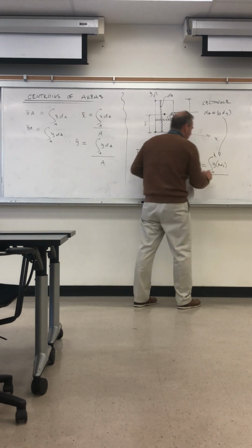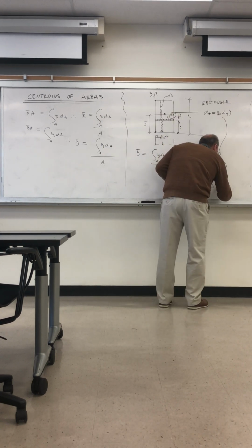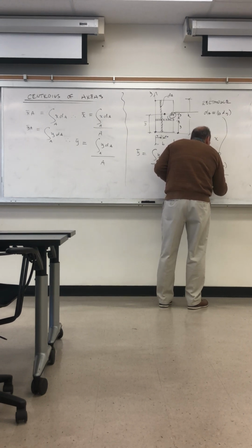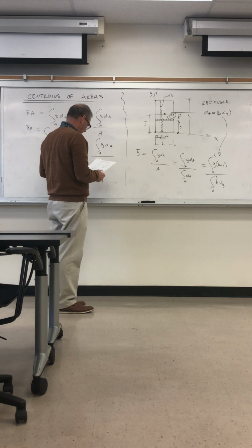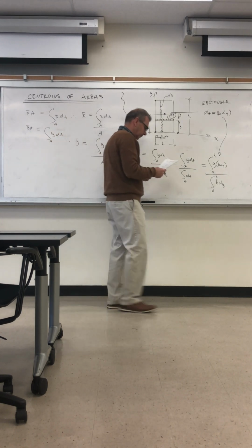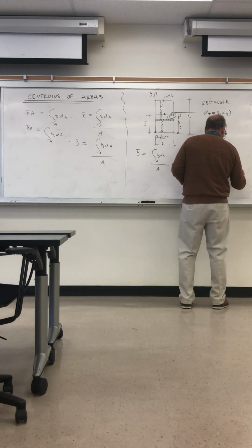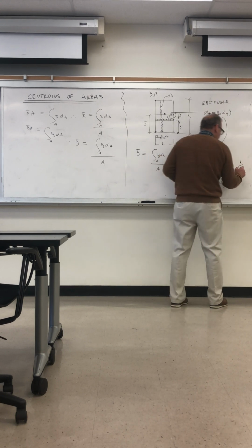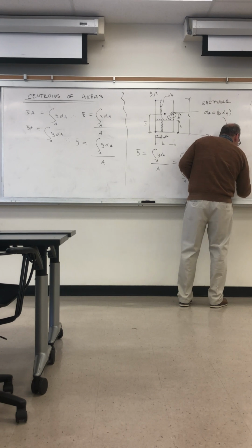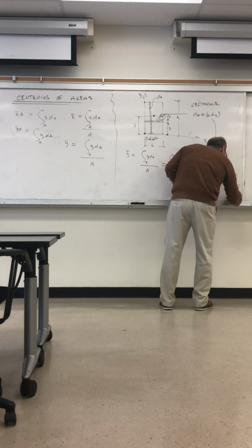And then this is the integral of dA, which is b dy, from 0 to h. I can take out b. So I get b integral from 0 to h of y dy, divided by b integral from 0 to h of dy.